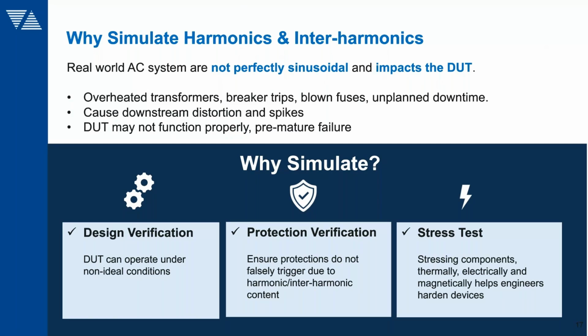So the intention of simulating is basically for design verification, right? So you can see how your device operates under non-ideal conditions, and also protection verification to ensure that your device does not falsely trigger due to some harmonic event or interharmonic event, and to stress test your device, to stress test your components thermally, electrically, magnetically, to really harden your devices to be able to withstand these types of events.